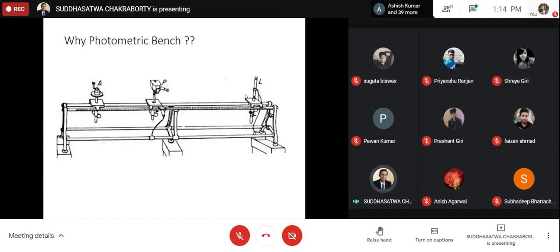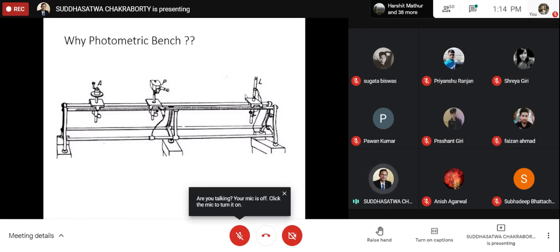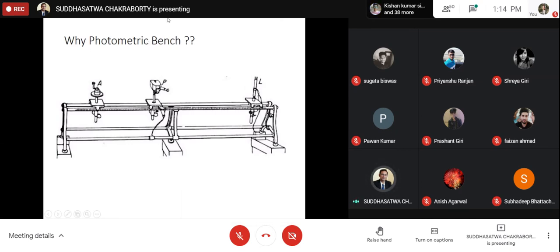Different angles we need to vary. Already I have told you that at different points the intensity will vary, in the horizontal angle and the vertical angle. So that's why I have told you that somebody specifying an intensity value of 30 candela doesn't make sense, because we need to specify at which angle of theta and which angle of phi. So that's why the 2D matrix I was talking about: if we forget about the vertical plane, in a horizontal plane, if I want to plot the intensity value, what is it going to give us?